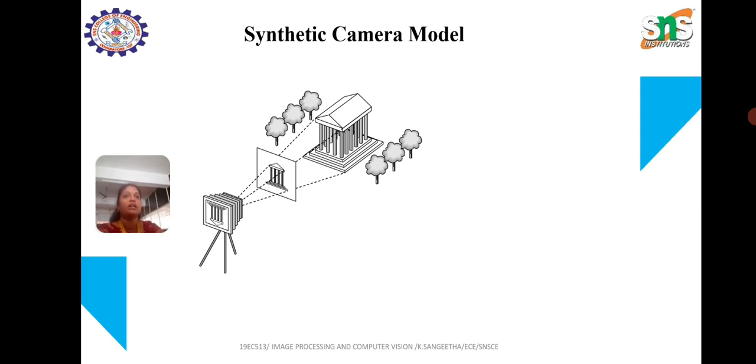So the image sensor converts the light into an electrical signal which is then digitized. The resolution, the number of pixels in the image sensor, determines the image detail, and the ability to capture variations in brightness is called dynamic range. And the measurement of the perception of light in the scene, how it translates into pixel intensity. The physical measurement of light energy intensity depends on the illumination, surface reflectance and sensor sensitivity, and is called radiometry. And photometry is the perception of light by the human eye, including concepts like brightness and color. So this is called photometry.